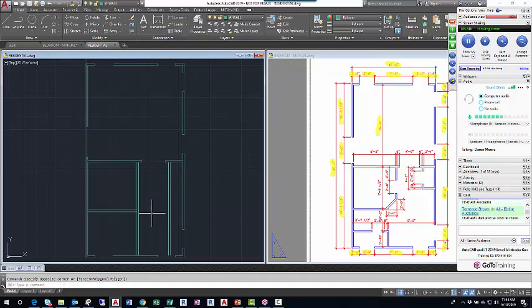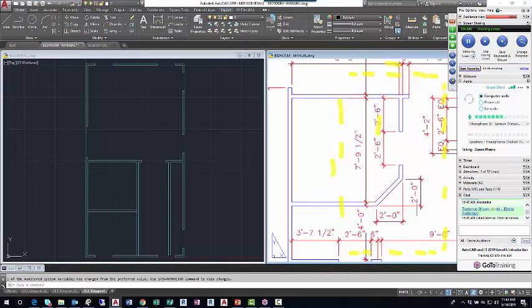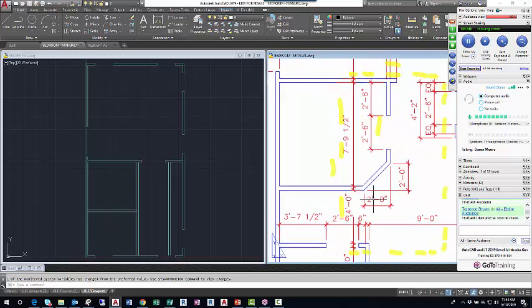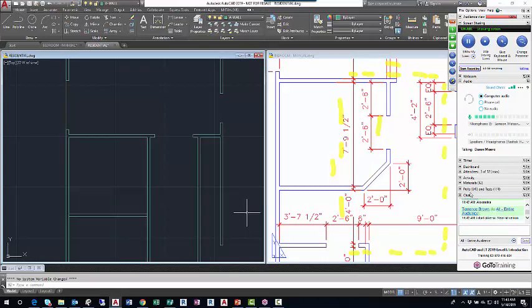All right. So we've got 4 walls of our floor plan, or this closet drawn in. So I'm going to use the chamfer command. This will be a new command. Again, I'm going to zoom in. It's going to look a little weird because of the highlights, but the chamfer command asks for distance 1 and distance 2. They're both going to be 2 feet, but the lines we're going to select will be the bottom horizontal and the rightmost vertical, or the outside lines of this closet. So it looks like this.